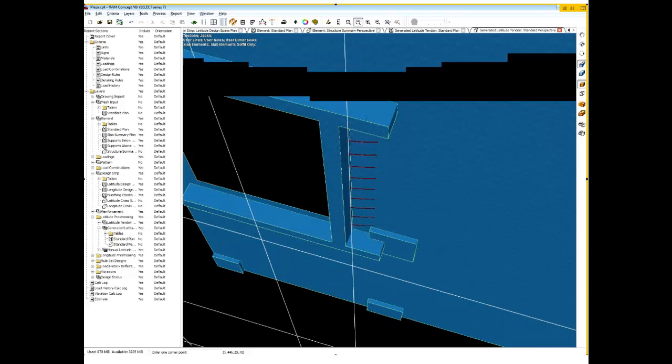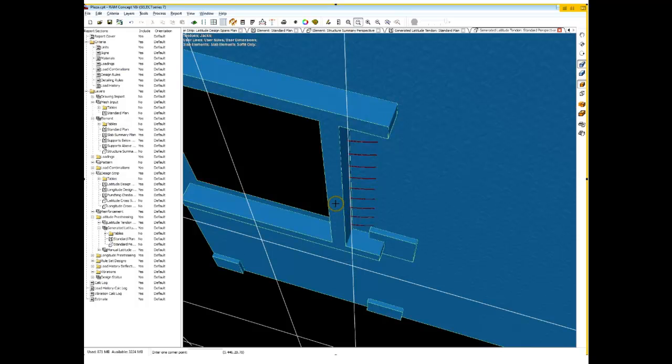The tendon was put in place right to the edge, and then it's given a certain elevation, but now the beam is in this location as well. So just that drape is causing it to jump between the slab and the beam. All right, so that's a problem, and that would be something definitely that we would have to go fix. And we will fix that through altering either the parameters or putting in some manual tendons in this location. All right, so I'm going to put this warning on hold for right now.